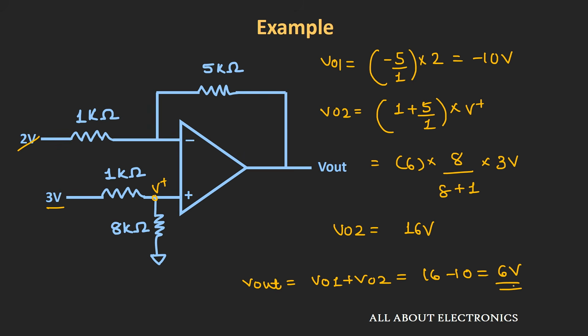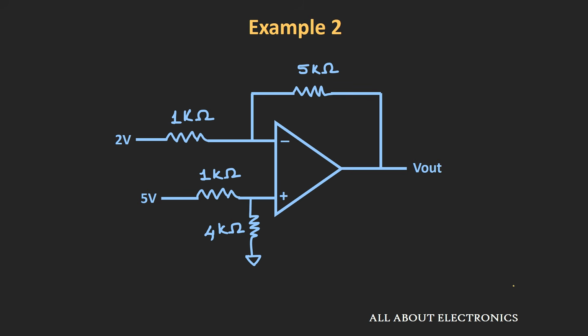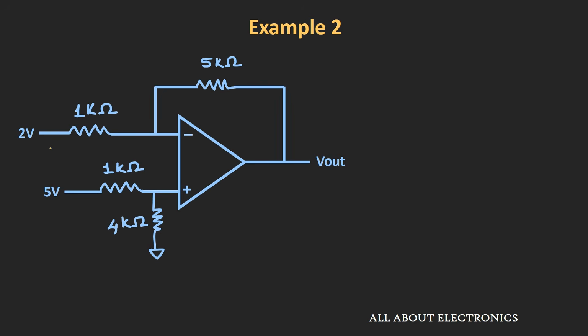Now here you also need to consider the biasing voltage that is being applied to the differential amplifier. So let us take one more example and we will see how this biasing voltage can affect your output. If you see this example, this is very similar to the previous example, but here let us assume that our bias voltage is plus 12 volt and minus 12 volt, and we want to find the output voltage. So here once again we will assume only one voltage source is acting at a time and we will find the output voltage, and then we will combine the individual responses.